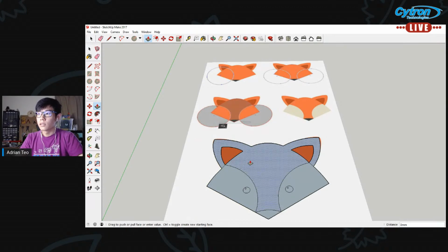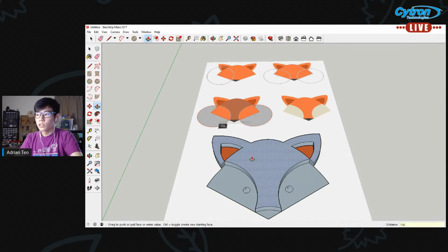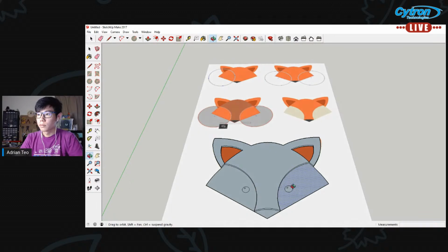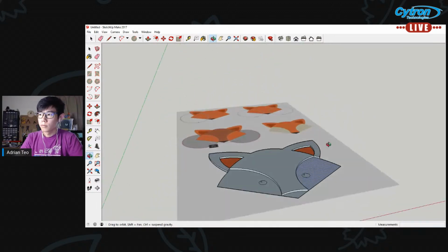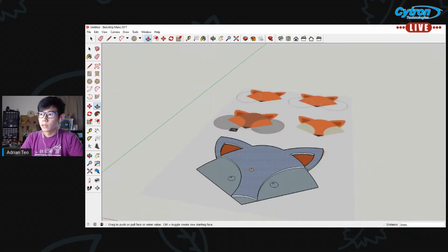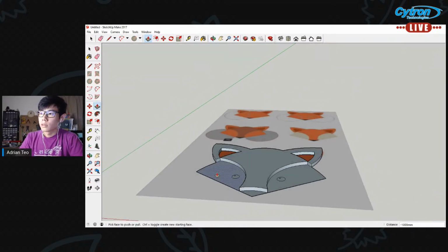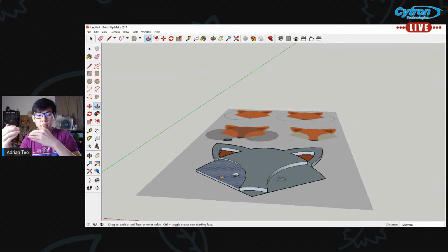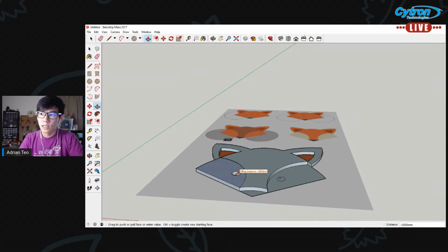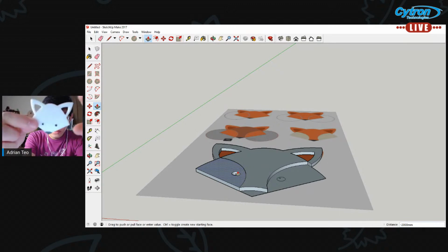Okay, I have to keep the line at 1000. Okay, now it's floating. I'm going to make it another 1000. And then I'm going to extrude this. I don't want every different shade, every different color of the picture to be at the same height. I want it to be different, with different depth.